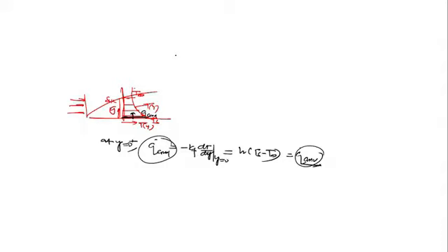Listen, this is a series. Whatever heat transfer is propagated through the wall by conduction, the same is going to be transferred at steady state. Let's say 200 watt is the rate of heat transfer by conduction. The same 200 watt is going to transfer in the rest of the fluid by convection. Yes or no? The same 200 watt in the rest of the fluid is transferred by the combined mode. Whatever 200 watt is transferred near the wall by only random motion of the molecules, by conduction, the same 200 watt is going to propagate in the rest of the fluid by the combined mode.